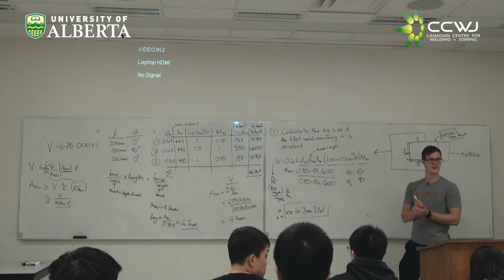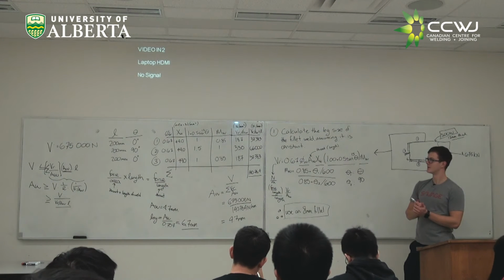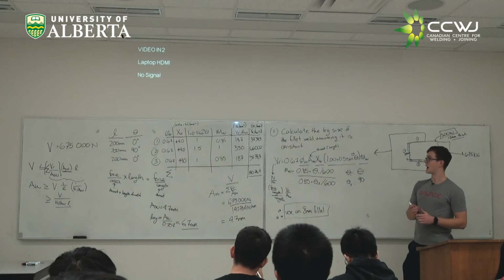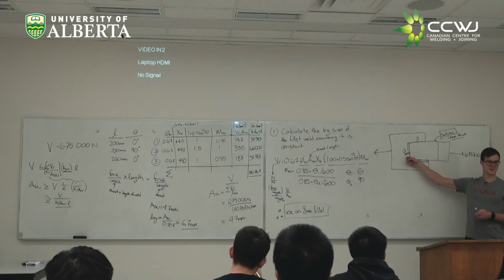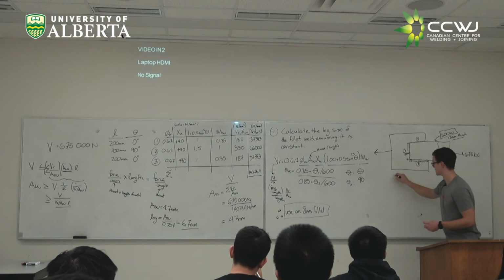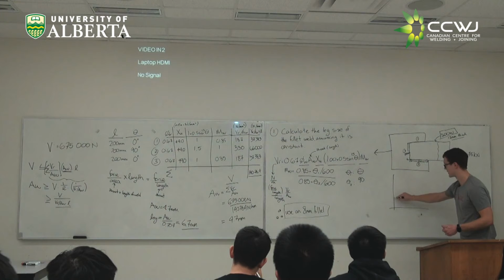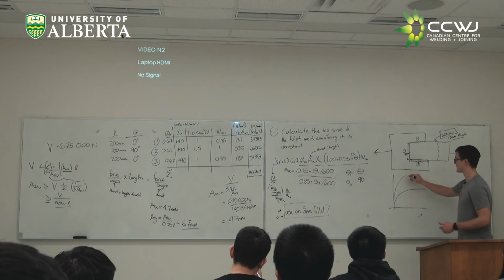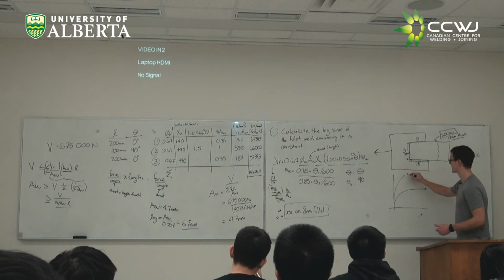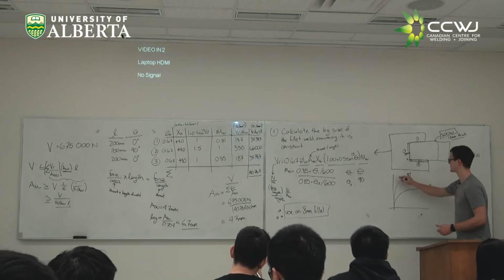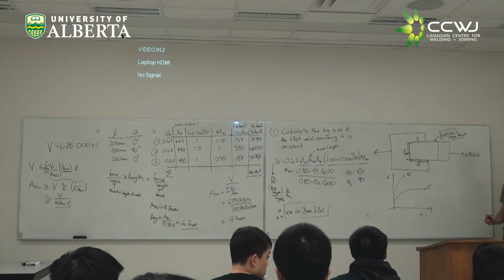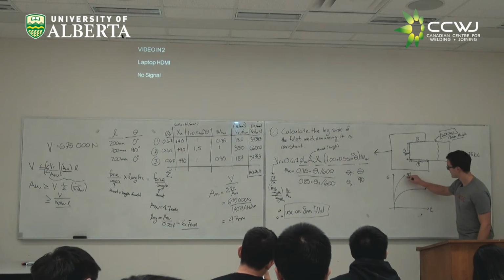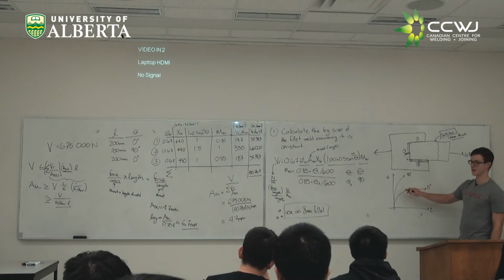So the second is higher for VR over AW times L? Yes. Higher than 1 and 2. What's happening there is, because it's a transverse weld, we showed some graphs in class, where if we had stress strain curves for different welds, we had something that looked like this, where this was at 90 degrees and this was at 0 degrees. Does everyone remember that? So if we look at this weld, it's going to fail on a curve like this.